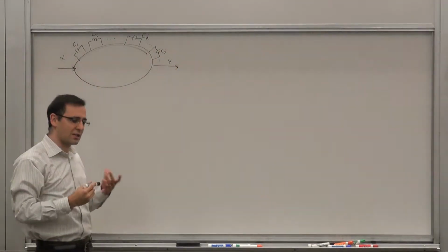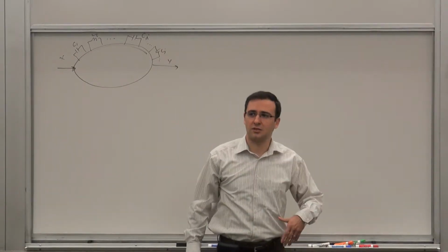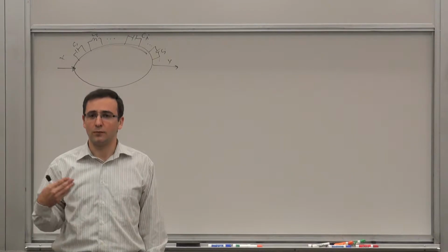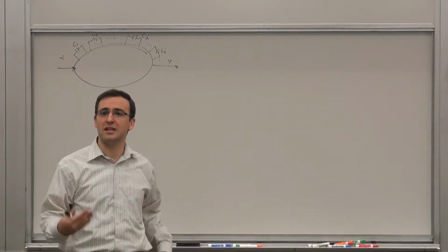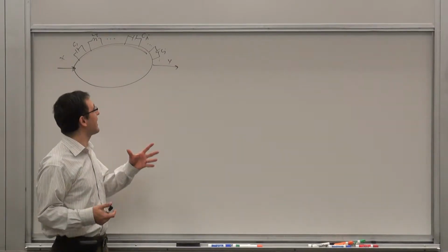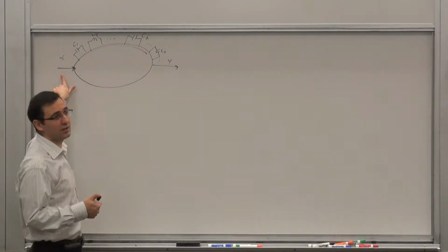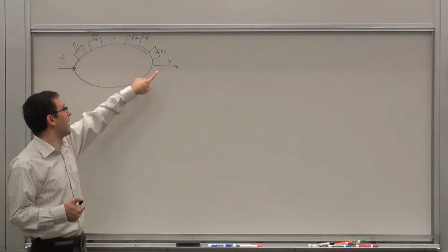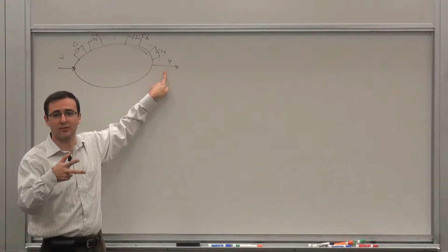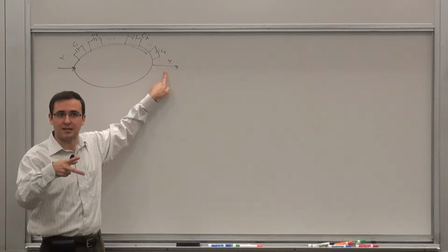And we talked about this briefly last time, so I'm going to mention it again. The x and y are voltages and current of ports. Now, the x and y can be the voltage and current of the same port. In which case, we define the input as the current of one port and the output as the voltage of the same port. What you're measuring, the transfer function, is really an impedance.